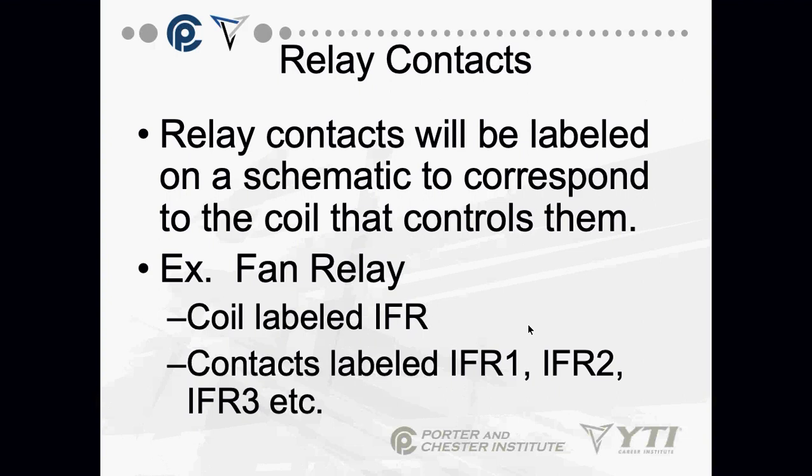Okay, the coil is labeled with a letter designation. The contacts have to be labeled with the same letter designation, and then you can add a number on it, like 1, 2, 3. Okay, this is why labeling starts becoming so important.